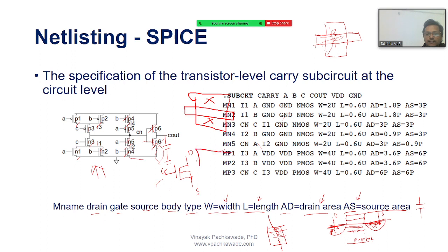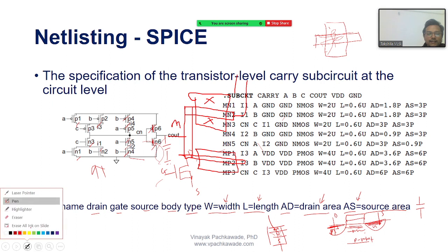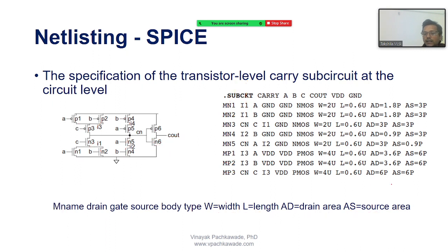And there was another transistor right here, and again you have this polysilicon right here. So these two polysilicons got connected through the metal. Okay, drain got connected to the VDD, so we use the metal for routing, right? So metal has some resistance also because they are wires, right? So the wires in the circuit will actually give the resistance in the circuit.